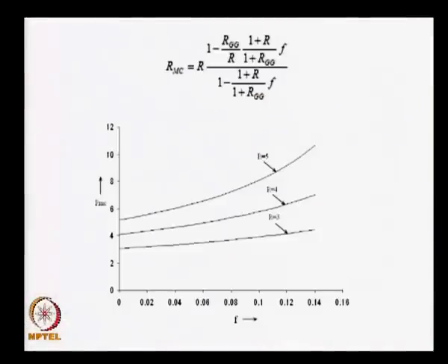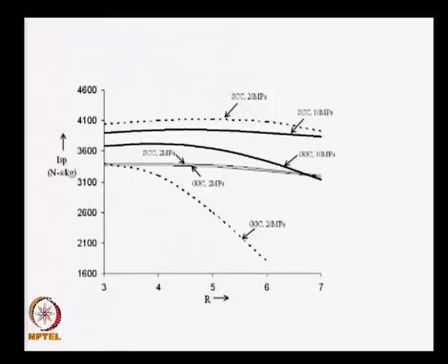We go back, we said this is the fraction I have calculated, I come back to this a little later. All what I am saying is, if I operate a gas generator cycle at a small value of pressure, this is the net value of specific impulse I get. If I operate the same engine on a staged combustion cycle at low pressure, I get a slightly better performance because I have not lost very much because F is still small. I still find gas generator cycle is lower than staged combustion cycle, but the loss is small. The loss is small because F might be something like 0.01 or something. If I go to slightly higher pressure, what is it I find?